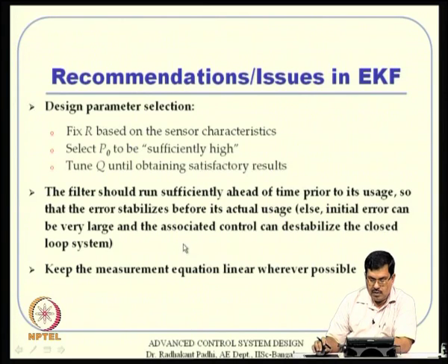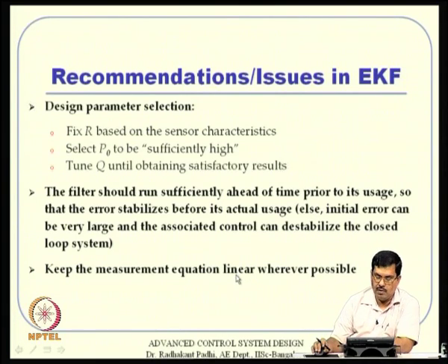There is another recommendation I have seen many times, that a lot of people are in favor of the idea that the measurement equation should be linear as much as possible. For example, the theory tells that I can linearize the measurement equation as well and obtain a C matrix. But in general, a lot of practicing engineers who work with EKF have observed that if you keep the measurement equation linear wherever possible, then it leads to better stability properties of the filter. That is just some sort of an experience recommendation. There is no theoretical reasoning to back it up.